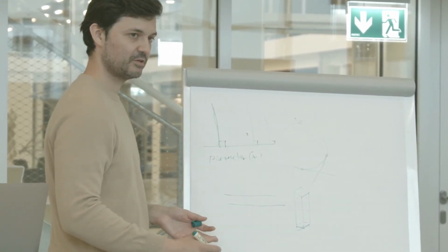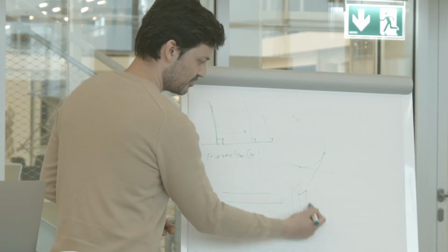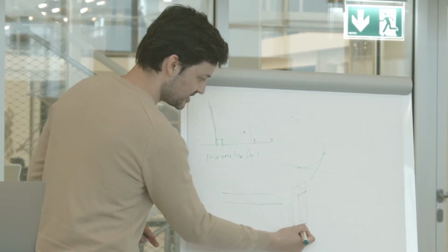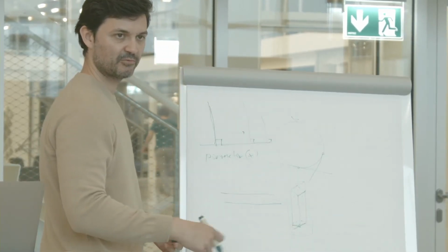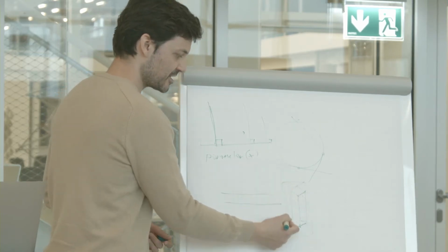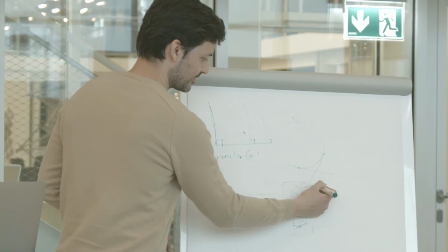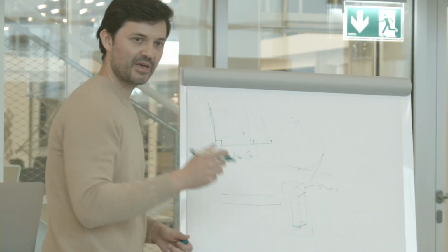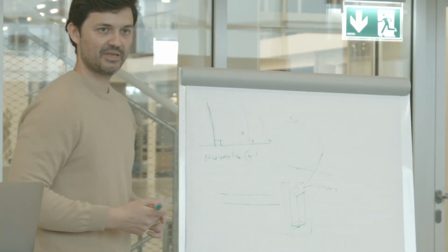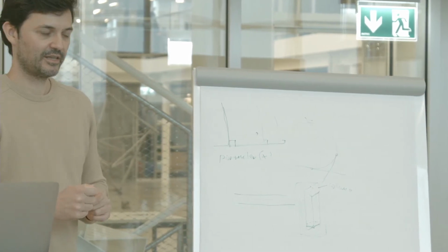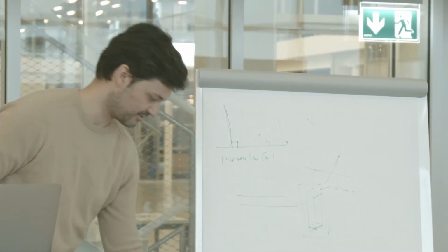He would say, what you need to do is group. Yes, this is six faces, but what I'm interested in is defining this as an element, and I want to say, this is a column. So I need to make a grouping of this and name it somehow, yeah? And then see how many of these things we have.